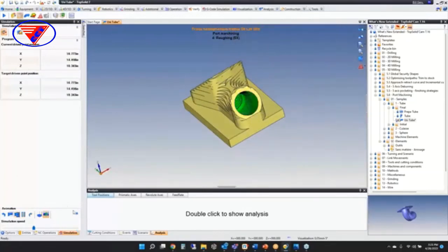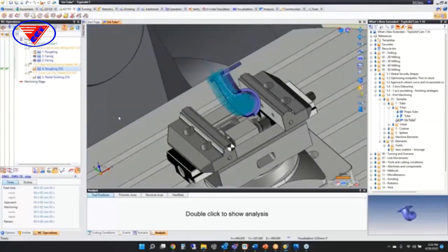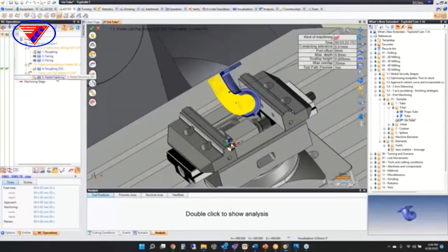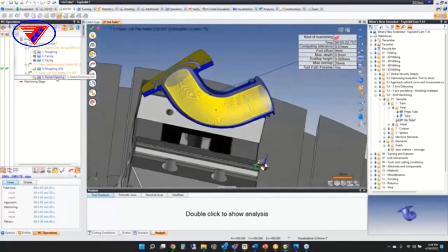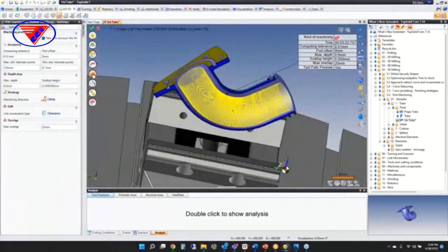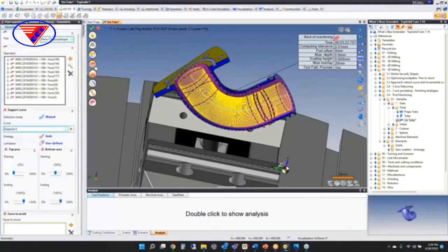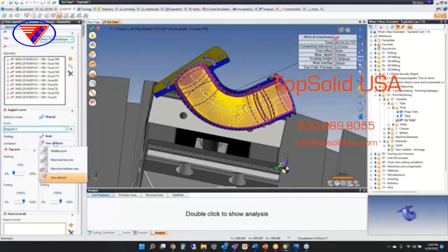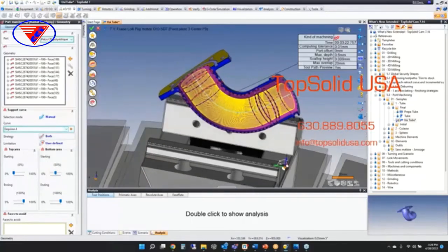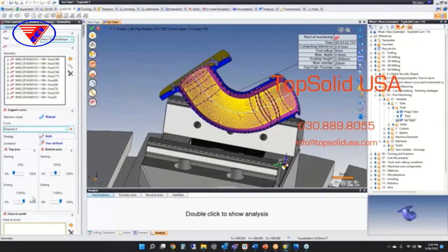Now, just like the roughing, the finishing is again a similar command. It's just finishing toolpaths instead, right? So you have your standard finishing toolpath strategies, but most importantly under geometries, again, you're coming from both directions, the limitation, how it's being defined, and then you can even play around with the top and bottom areas where you can drag the starting and ending position of the tool a little bit to tweak your toolpath.